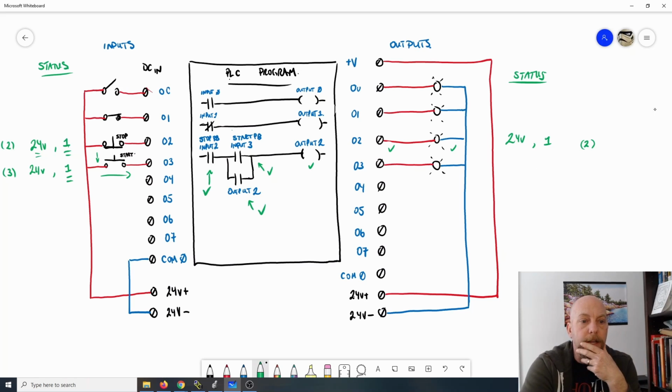We're just looking at this particular bit to see that it's a 1. We're not looking at an external contact that corresponds to output number 2. We don't have any other inputs that correspond to this coil, so we have no external confirmation that it's on. We're just dealing with the bit that's internal to the PLC that has gone from a 0 to a 1.